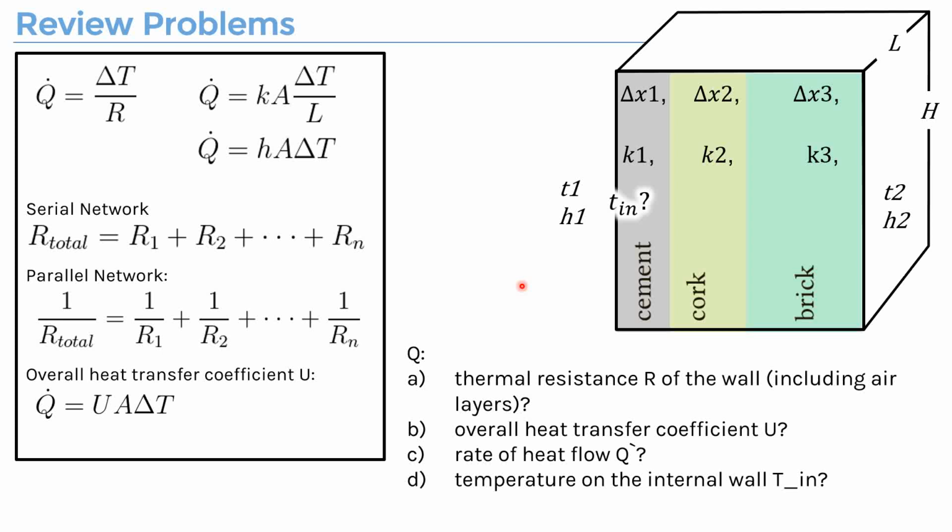You will notice that although we try to utilize a form very similar to convection, this part actually contains both convection and conduction. These two can be easily converted, but in this course we prefer the overall heat transfer coefficient because, for example, if we use resistance, when the resistance is high, we would say it's a good insulation.